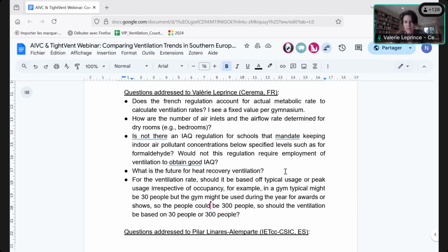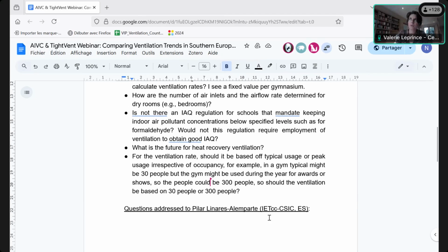And the energy performance regulation is really rewarding demand controlled ventilation. So when you do the energy performance calculation right now, you don't save that much energy with heat recovery compared to a humidity-based demand controlled ventilation. And it's much more expensive. So that's why we don't have much of it.